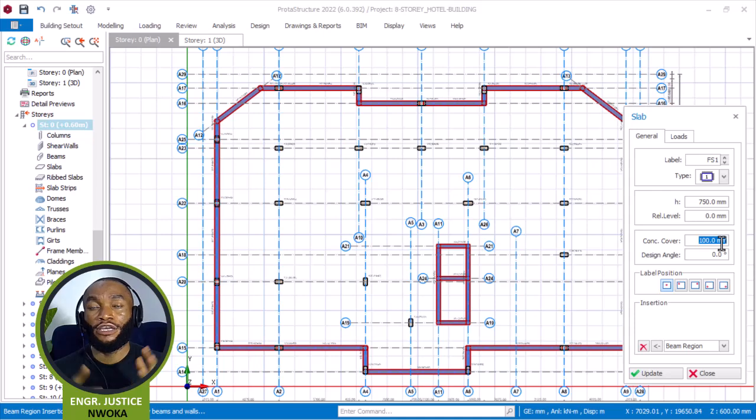and UK, the minimum concrete cover that you can use for a foundation is 50, right? Based on Eurocode. American will tell you the minimum should be 75, okay? When that's for foundation, or when a concrete member or a member of structure is directly in contact with soil, the minimum to be used is 50 millimeter. That's for concrete cover in terms of Eurocode and BS code. Okay, so in that case, since you're using Eurocode, I'm going to type 50.